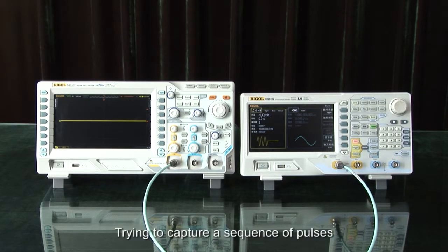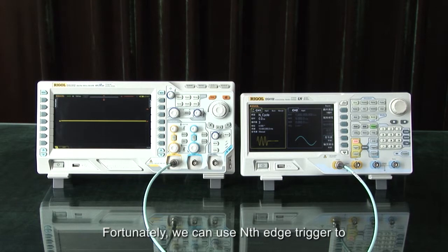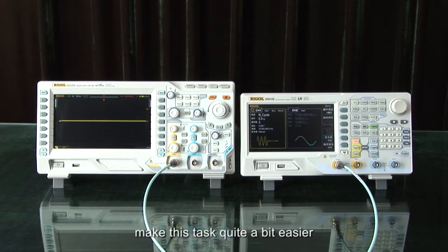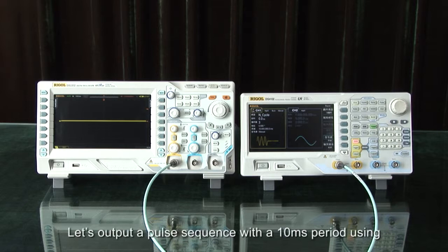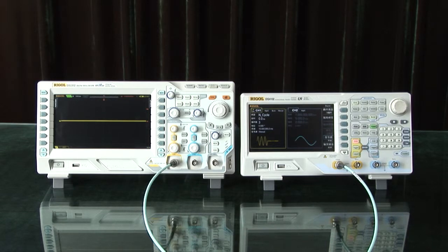Trying to capture a sequence of pulses with standard edge triggering modes can be difficult. Fortunately, we can use nth edge trigger to make this task quite a bit easier. Let's perform a brief experiment. Let's output a pulse sequence with a 10 millisecond period using a Rigol DG4000 arbitrary waveform generator.